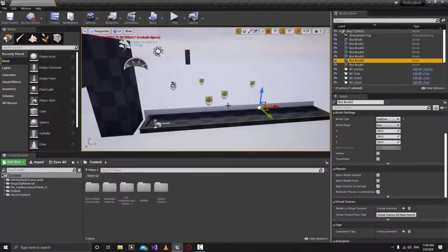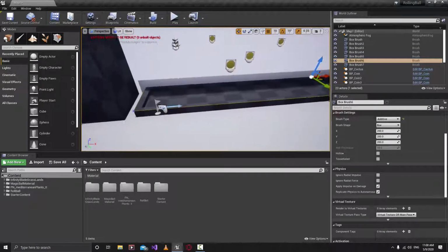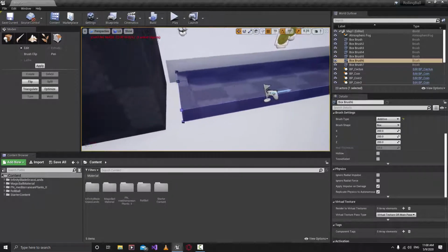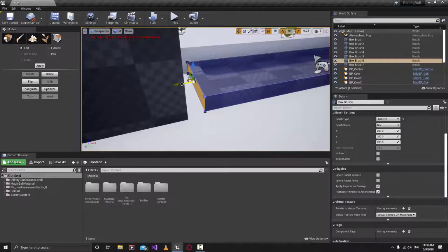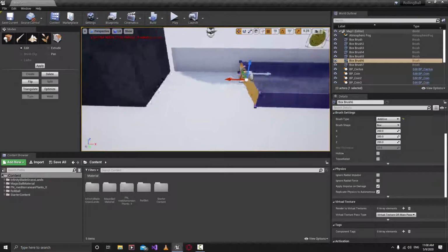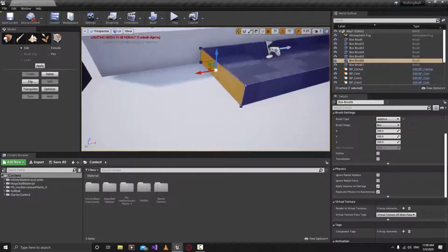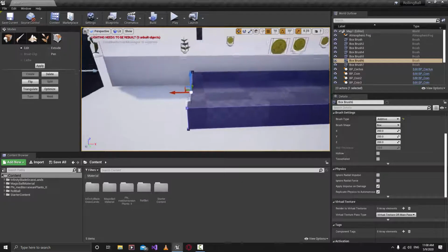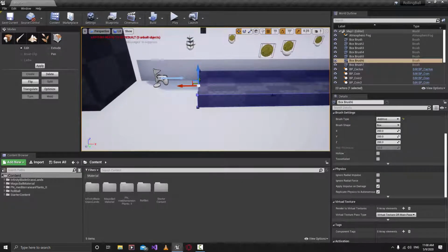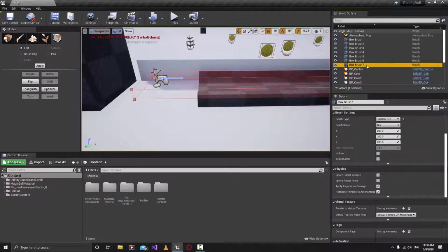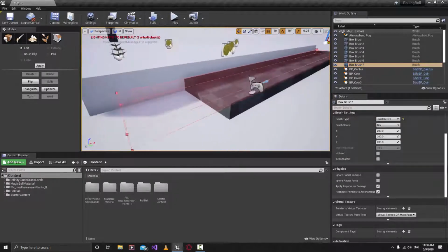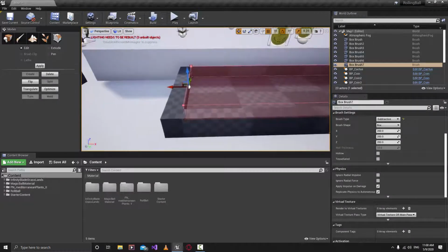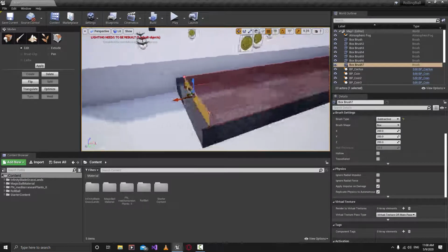All right, and then what we need to do is go to the geometry editing tool and make sure we grab that face and make it something smaller like this. And right now you can see that it's gonna carve out that edge too, because what we did is, we grabbed that box and we did not grab the box 7. Right, make sure to grab the box brush 7 and select that face as well, the subtractive one. And yeah, I think that is just fine.